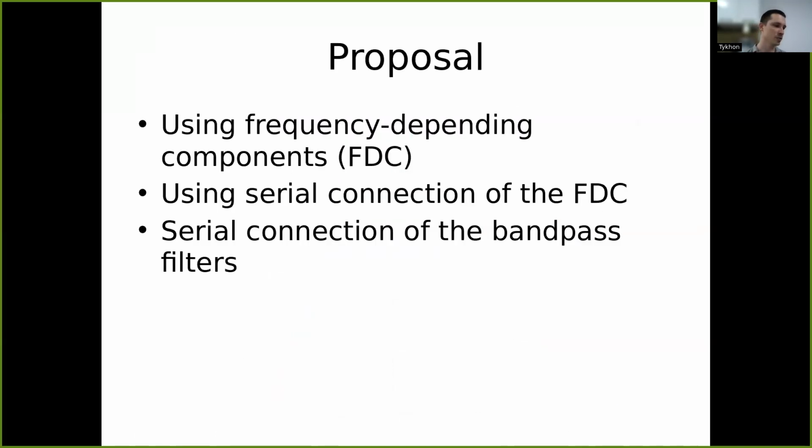In the sensor signal processing channel, typical tasks are changing the cutoff frequencies and bandwidth, as well as the steepness of the fronts of the amplitude frequency characteristic. The aim of the work is to analyze the use of a serial connection of the same type of digital filters and improve the approach for calculating the cutoff frequency of a new connection. Such a connection makes it possible to increase the efficiency of the information control system in an autonomous mobile robotic system by reducing the bandwidth and increasing the steepness of the AFC.